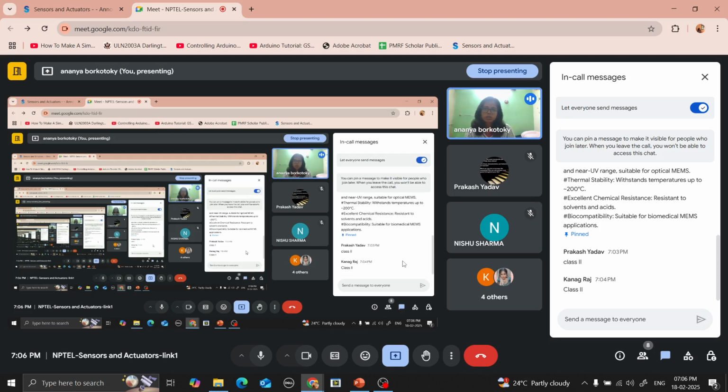Now, what is the difference in the case of class 1? It basically protects the person and the environment, but not the product. How? In that hood, the air from the environment goes inside without going through any filter.